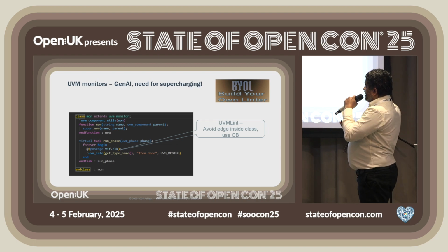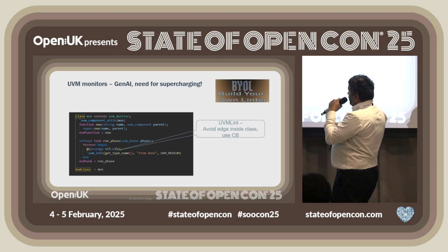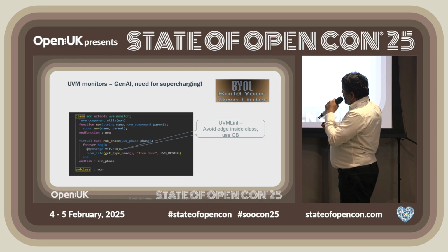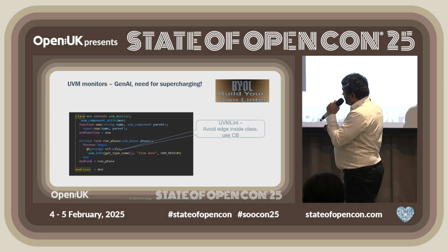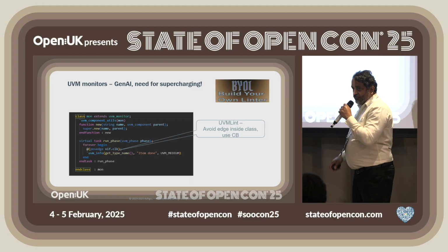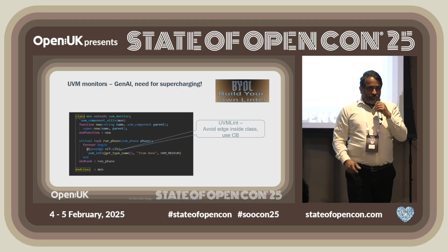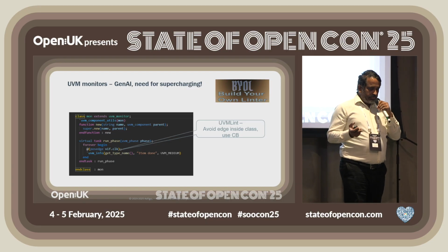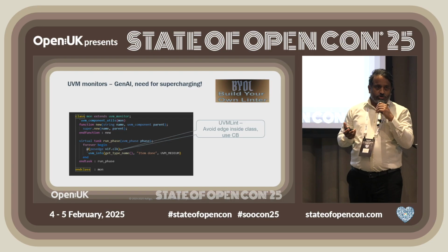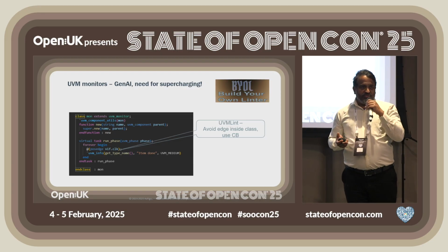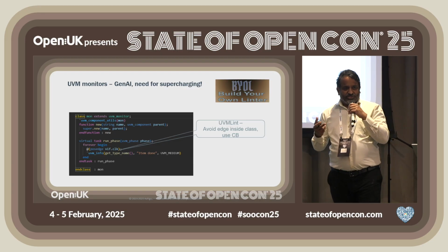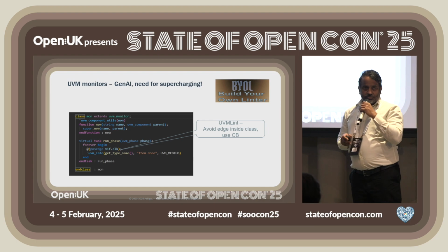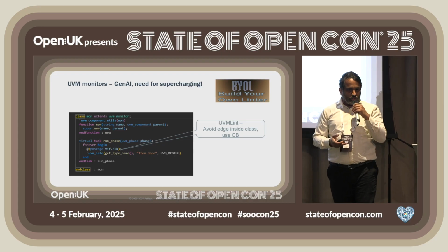Now, this generates a class monitor extends uvm_monitor. All this code is nice, and it's also very well indented, etc. It has a run phase, all good, but suddenly look at this, it starts using posedge vif.clock. For those who do not believe me, there's a gentleman named Dave Rich, if some of you know him. He works for Siemens EDA, Mentor Graphics, and they run a forum called Verification Academy. There's a nice user forum out there where you would see why you do not want to do this. It's going to be race prone, and harder to debug.